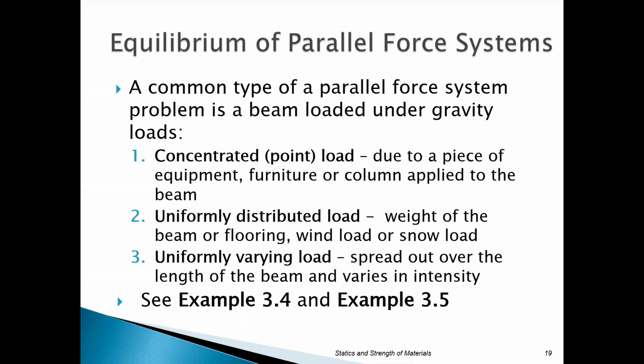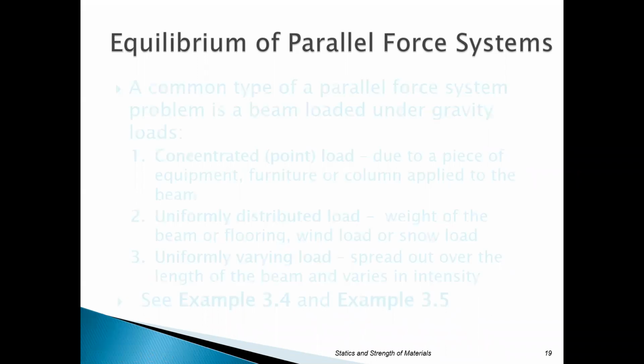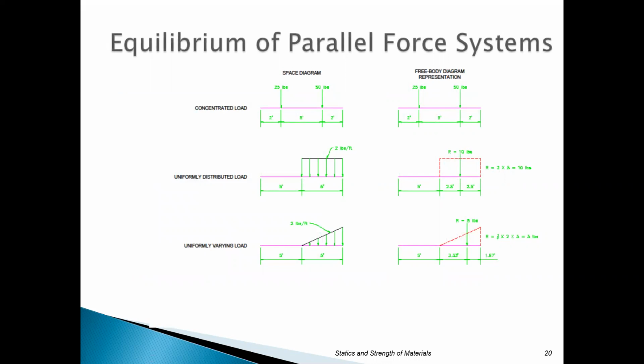So what we do is basically take these and bring them down into a concentrated load when we handle them as a parallel force system problem. Now, you will see when we get, I think, to chapter 11, when we start talking about shear moment diagrams, we will take these and break them down to do the reaction. But once we actually get into the shear moment diagram, we have to consider the uniformity here. So we'll bring that back later. But that doesn't apply to us right now. So these diagrams should be helpful.